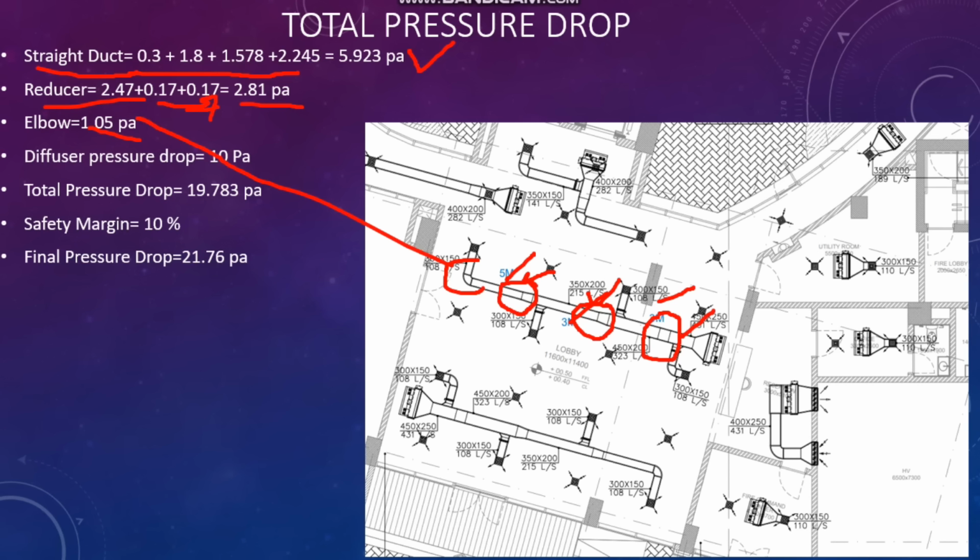So next, the important thing is the final one, that is the air terminal, or you can say here the square diffuser. So for the square diffuser, I explained how to select it considering the static pressure, neck velocity, throw and different factors. I have posted a separate video. Please have a look at that. And normally it is general practice that the static pressure drop we consider is maximum 10 Pascal. Some projects go with 15 also if the consultant doesn't have any special requirement. But it is a good engineering practice that you can consider the maximum pressure drop as 10 Pascal for the square diffusers.